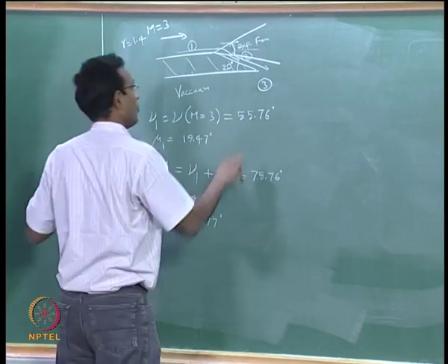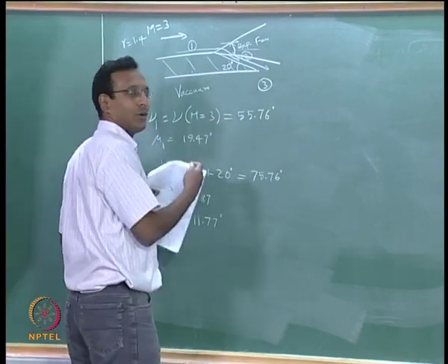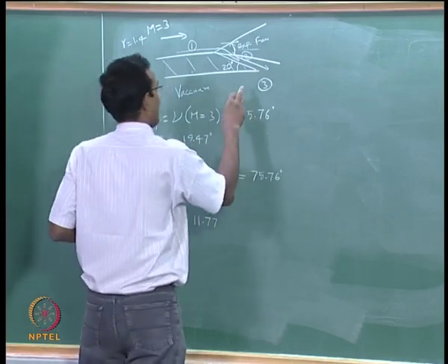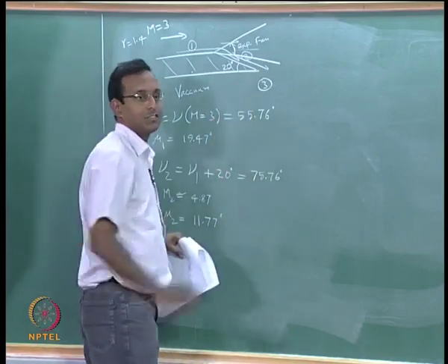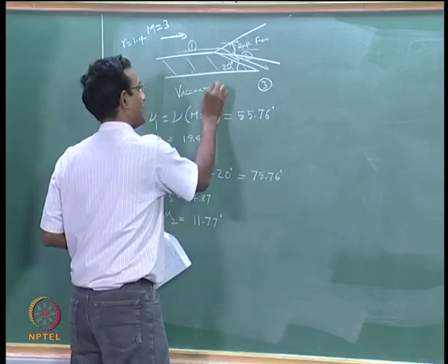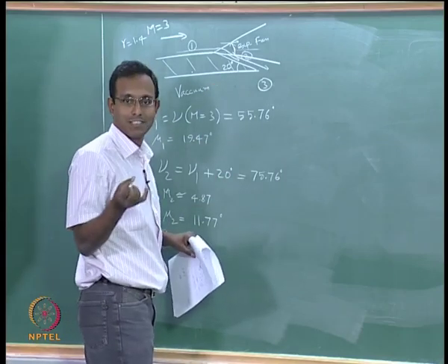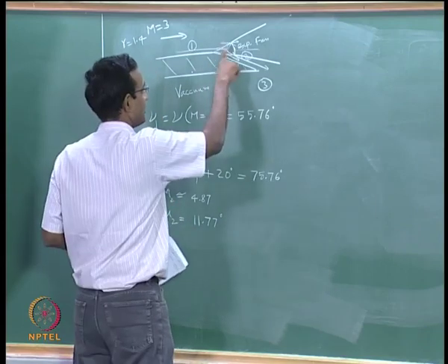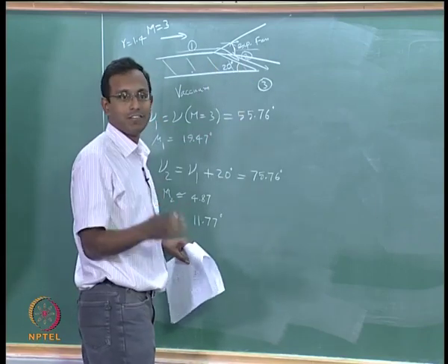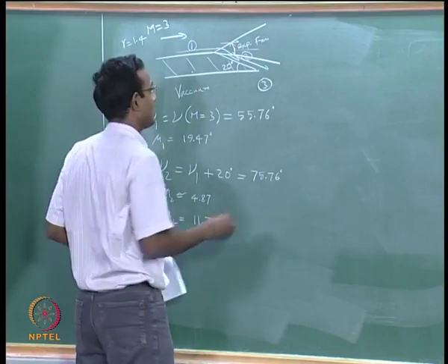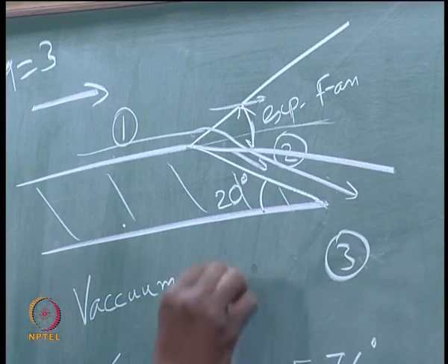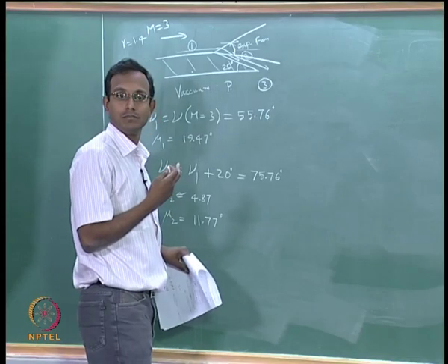Now, we will go out of that. I believe you can do that remaining part. Now, the next thing is we are not given any angle change, but you are given pressure outside. We said in gas dynamics there are two types of boundary condition, velocity direction and pressure. We have been using velocity direction till now, suddenly we are giving a pressure boundary condition. If I give a pressure boundary condition here, what should it be? I have to just go and find what is the pressure here. It so happens that P is 0.